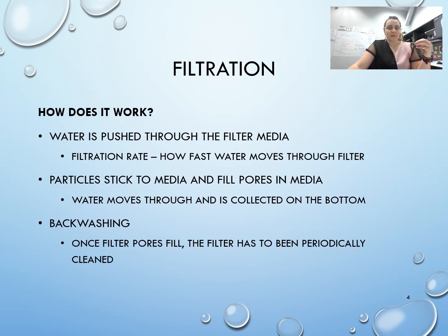So how does it work? Filtration is based off of the principles that out in the environment we have layers of sand and soil, and the water naturally trickles through those layers of sand and soil. And by the time it does, it's clean at the bottom. And the reason for that is because as we push water through a media, there are pores between the grains in our media, and any contaminants are going to stick to those pores or are going to fill those pores, but the water is going to continue to move through.